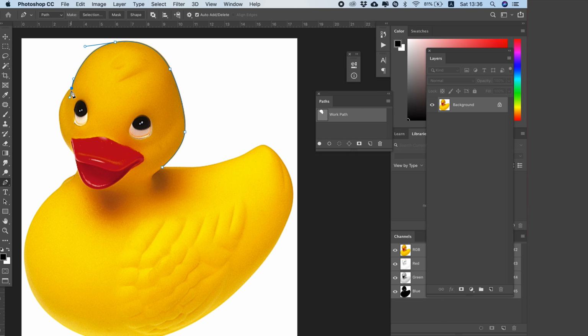Alright, now like this. Here we've reached a point that's different from the shape we were outlining or the shape we were drawing on. What can I use here? Let's see. I want this. We want to remove the curve here by pressing Alt and clicking on the point. On the point itself there, it's gone. Because if it stays, it'll pull in a way that's different from what I want. As you can see here, I remove it by pressing Alt and clicking, and it disappears, so I can start again as if I'm starting from scratch.